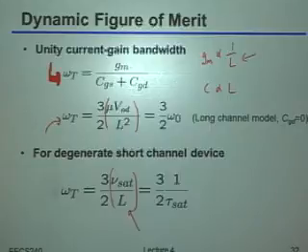So clearly, if you're operating beyond omega t, for most of the circuits we're talking about, it's just not even possible, right? And as we'll show a little later, once we've worked out all the different pieces of the model, as you get closer and closer to that omega t in terms of the gain bandwidth, the power will just start shooting up very, very quickly. We'll talk about that more in a second, but I'll derive the exact details in a few more lectures. Okay, it's a good question.